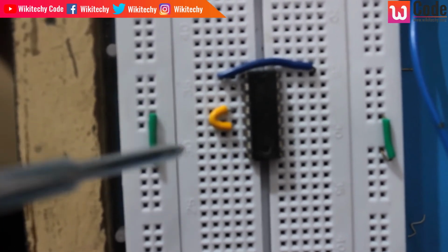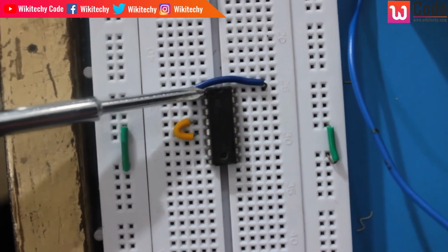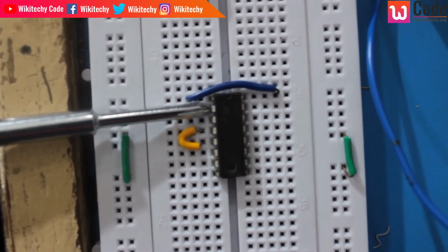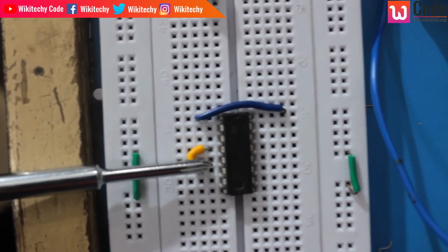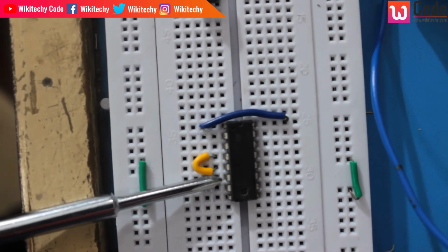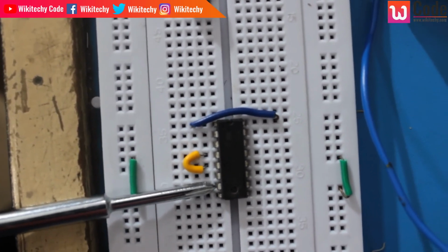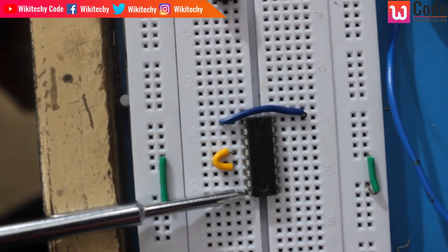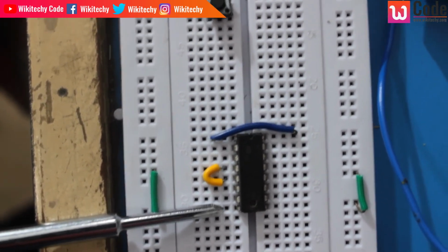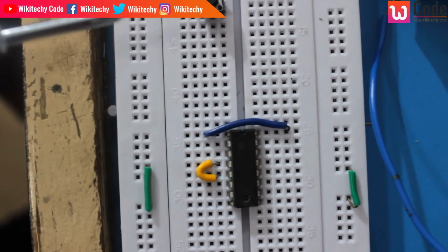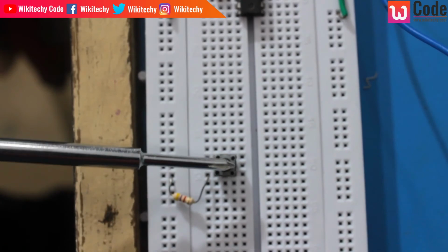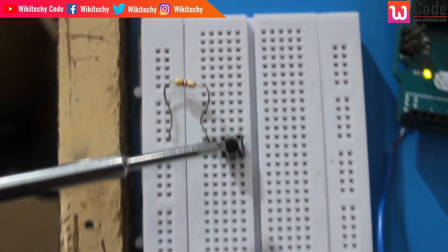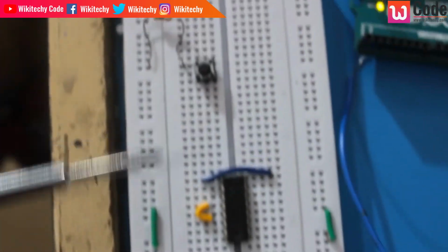So this is how it is, and over here first pin is enable, the second pin is for input 1, the third pin is output 1, these two pins are ground, and this pin is for output 2, input 2, and finally we got the motor input. Over there I'm trying to give the voltage from the battery, and apart from that we got two push buttons, one and another push button here, 2. These push buttons are used to control the motor on, and this push button is for off. That's how. So we got the circuit ready.